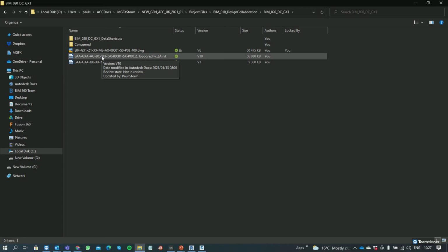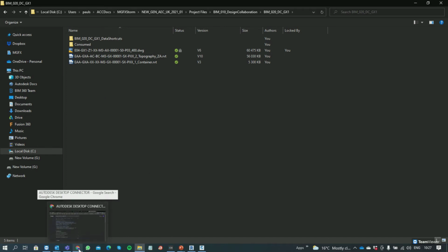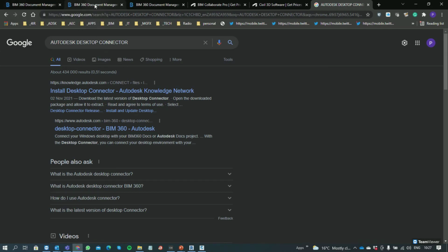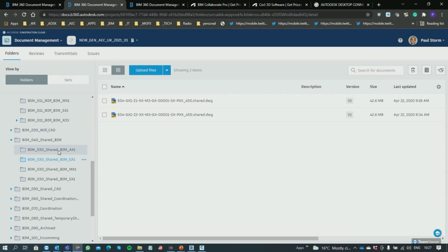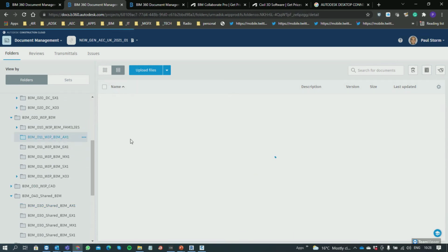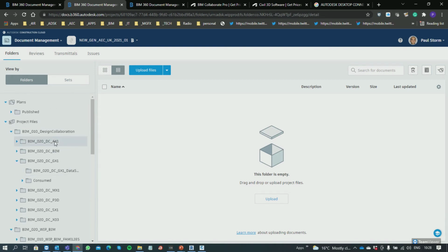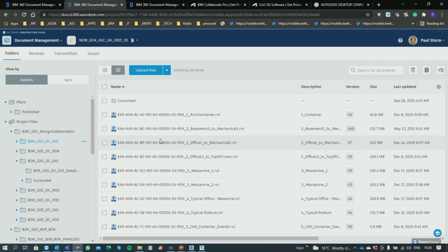But in essence, with Civil 3D, only one person at a time would be able to open that file. Note also, just something to keep in mind when you use these projects, is that with Revit, the first synchronize that you do onto the cloud will be the version in which the project is initiated. If it is a later version than the version that somebody is using on your project, then you will not be able to revert to an earlier version.